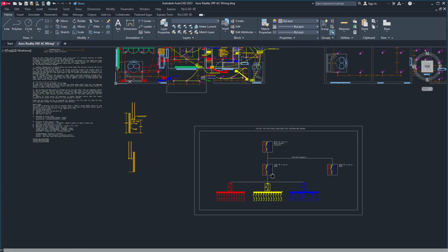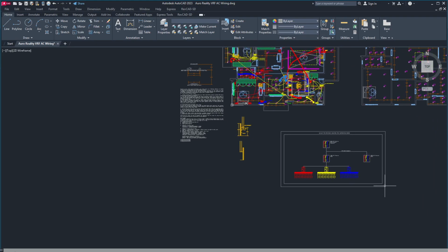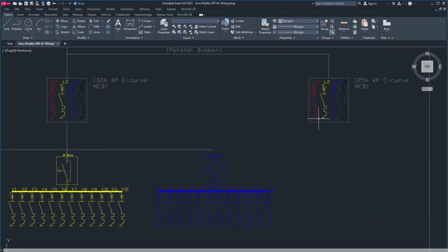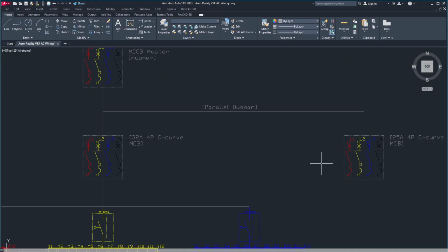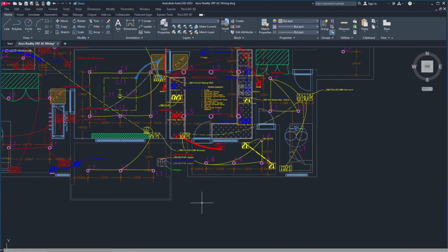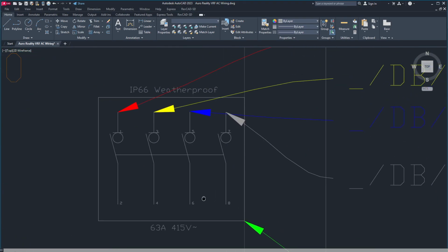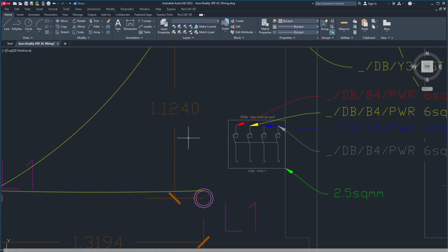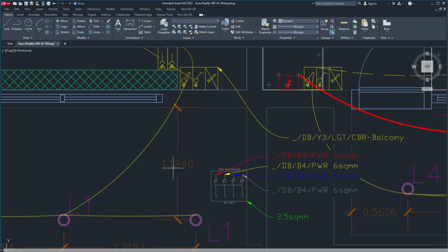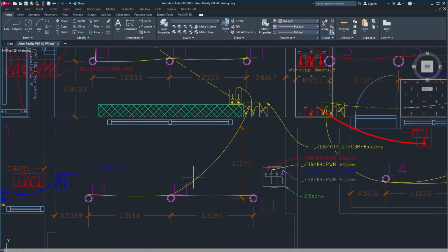This goes to the VRF. That means there are wires from here, 5-core wire. Okay, you do one thing. You take a 4-core wire, 6 square mm 4-core wire, and one earth wire you draw. One earth wire you take, 2.5 square mm earth you can take. From here you can take it and drop it in this isolator, and from this isolator you can operate your VRF. You can operate your VRF from here.